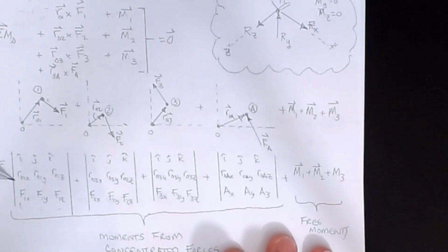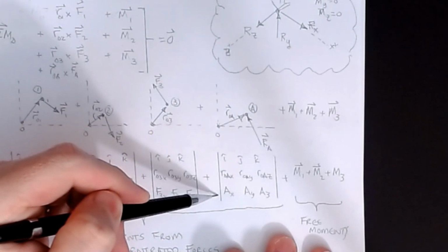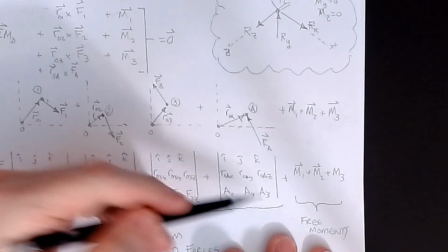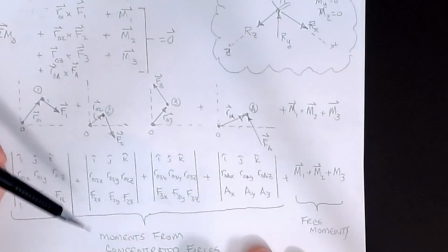Usually position vectors you know. A lot of times applied forces you know. Often supports you don't. So if you don't know it, you just keep the math operator here and keep them as variables, AX, AY, AZ, okay? And compute what you can.